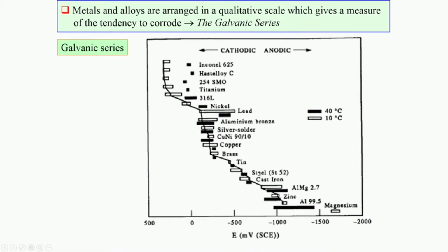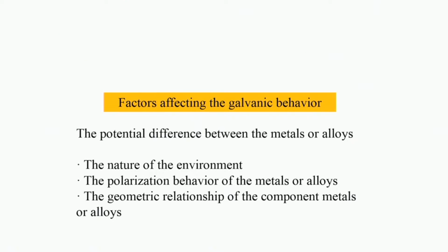But if you couple steel with aluminum bronze or steel with nickel, you will find that a lot of corrosion will be there because of galvanic corrosion. Similarly, if you choose zinc and titanium or zinc and stainless steel, you will find a lot of galvanic attack. So, whenever you choose material combinations, the galvanic series plays a very important role and acts as a guideline for the choice of material combination for a specific purpose.